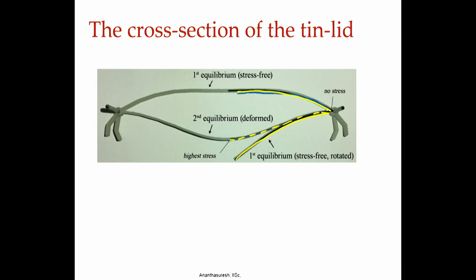That means that in the second state, this deformed one, this is stressed. So, there is stress in it, whereas the original one as fabricated is stress free state. That is how this bistable thing works. So, when it is in the other state and I apply forces like that, it is going to switch back to the other state. From here it will go back there.